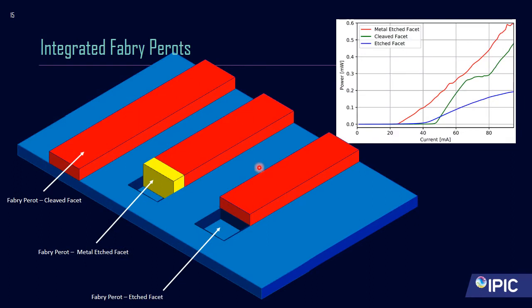When integrating a Fabry-Perot laser into a photonic integrated circuit, we don't typically use the two cleaved facets. Now granted, in a PIC we'll definitely need at least one cleaved facet to measure the actual output of the device. However, sometimes the Fabry-Perot would be in the center or at the very end of the device, and their lengths won't allow it to be stretched to the cleaved facet. So we have two separate alterations here.